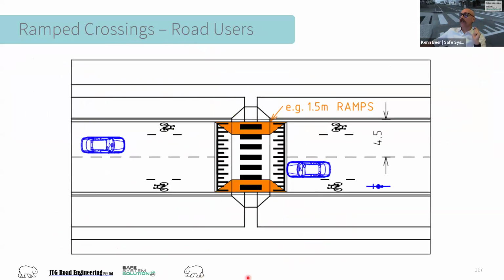And there were some specific comments that came in around some of the requirements there. Doesn't 1 in 14 require handrails on both sides of the ramps? And question of whether the recent standard has a maximum of 1 in 10 there. So I think you've sort of covered that. Yeah, no, that's great. I think in terms of handrails, that's for certain scenarios and includes mobility, but yeah, that's great. And I'll be happy to touch on that later. I think I'll just keep moving through the ramp crossing section now, though.